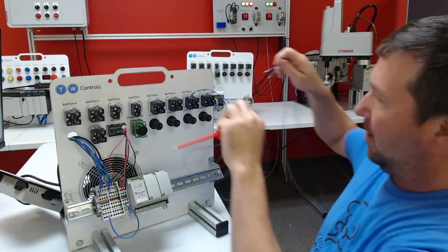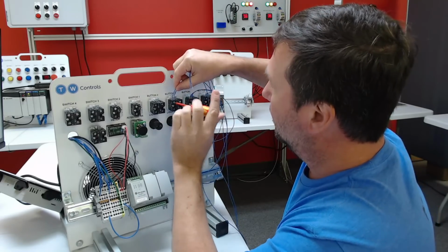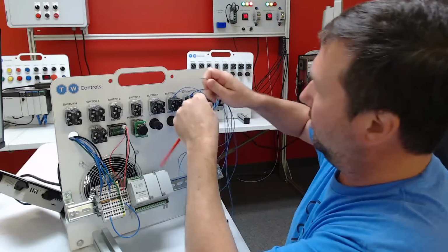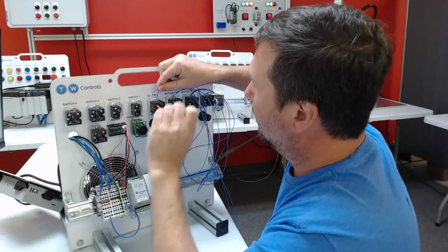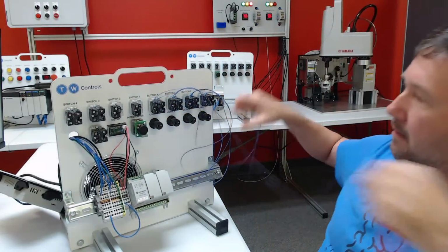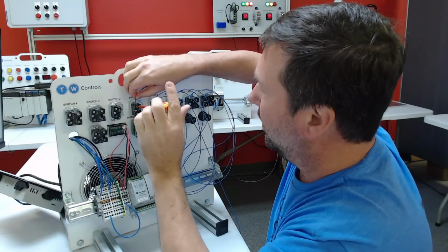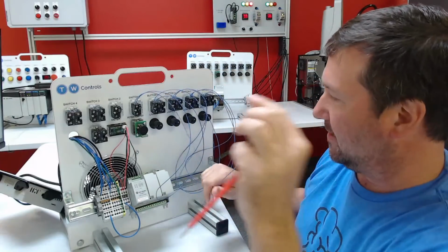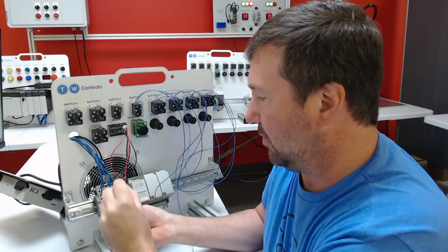And then I'll take that wire and another wire and put it in button 3. And then I'll take that wire and another wire and put it in button 4. And then I'll take that wire and an additional wire and put it into switch 1. So that is going to jumper all of these, and I'm going to connect this to our plus 24 volt. And that'll be any of the left terminals right here.